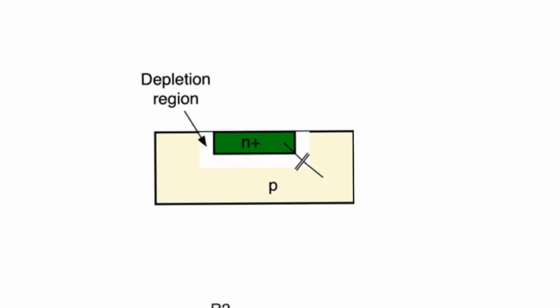Unlike layers that are created above the substrate, diffusion is created within the substrate. And therefore, it does have a capacitance, but this capacitance is through the depletion region that it forms with the substrate, because usually this p-n junction between the diffusion layer and the substrate is reverse biased. The only exception to this is when diffusion is used to create a body or well contact, in which case we will not have a capacitance. So this is just a depletion capacitance that can be calculated.